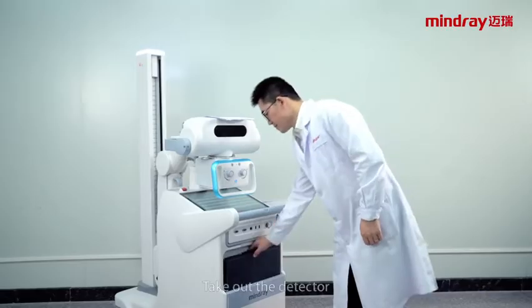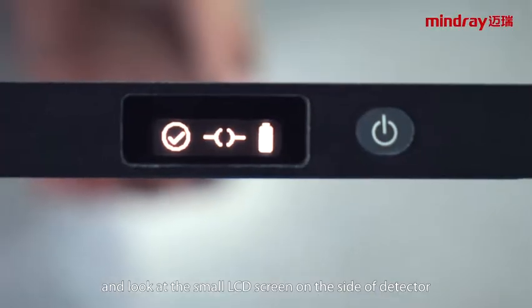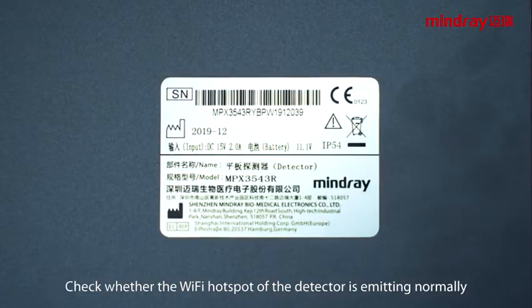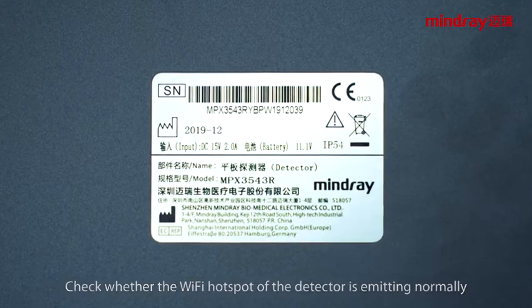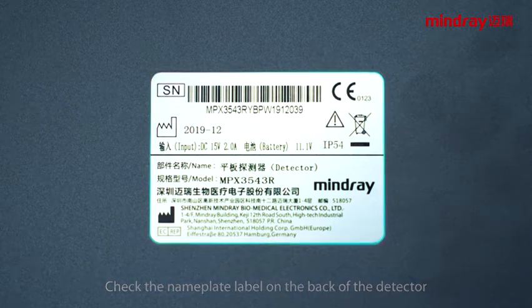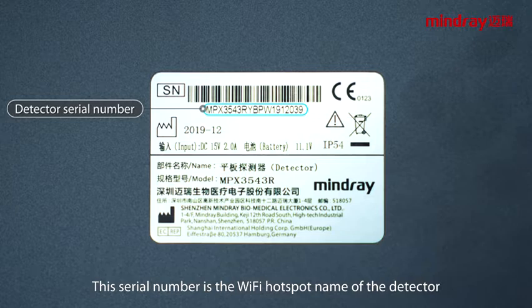So when the detector fails to connect, we can carry out the investigation from the following aspects. Take out the detector and look at the small LCD screen on the side of the detector. Make sure the detector is running normally by itself and there are no errors reported on the LCD screen. Check whether the Wi-Fi hotspot of the detector is emitting normally. Check the nameplate label on the back of the detector. Find out the detector serial number.